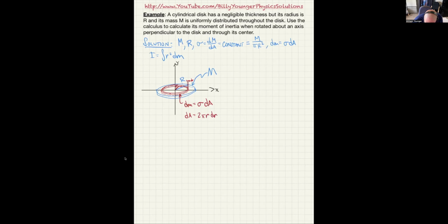Now, that's actually our differential area element, and we're completely ignoring the thickness, which might be called T or something like that. But it's not that difficult to extend this to 3 dimensions. The main thing is we're going to use 2 pi r dr. Again, technically dA should be exactly pi times (r plus dr) squared minus pi r squared. If you actually took the time to do that, you would get pi times r squared plus 2r dr plus dr squared, minus pi times r squared.